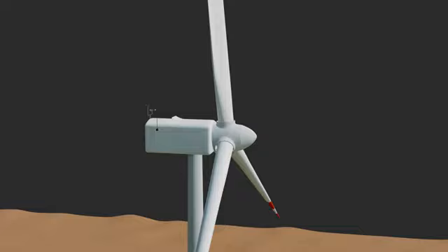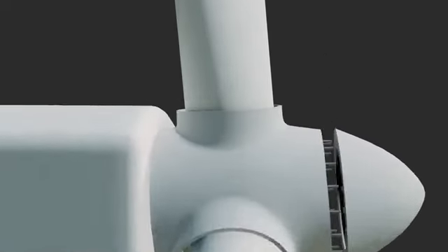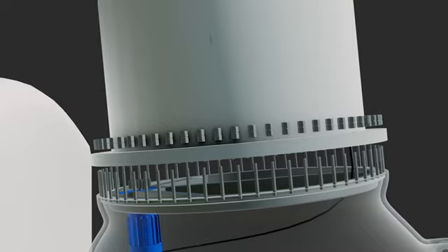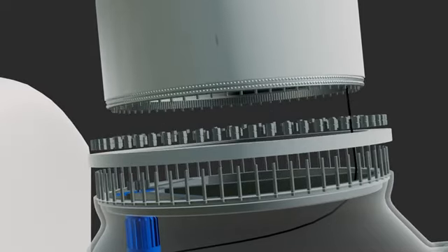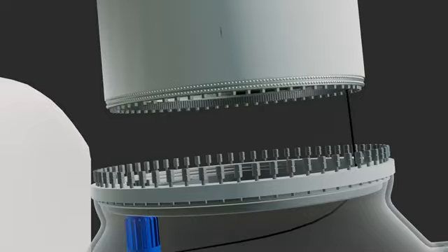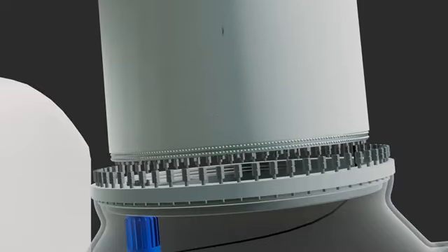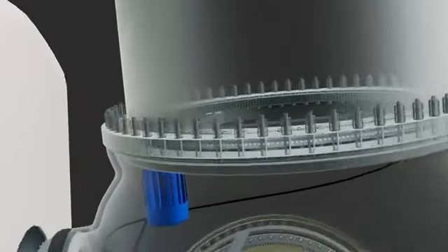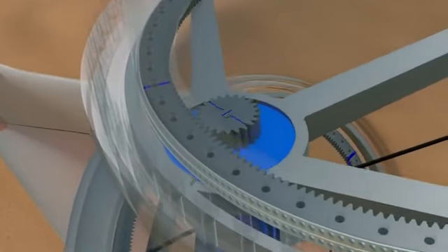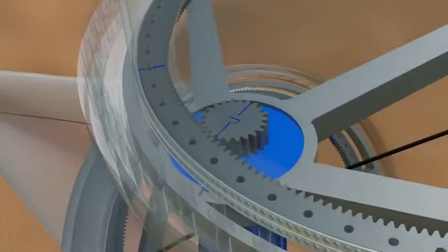An integrated bearing mechanism with an internal gear ring is present at the blade root. The outer ring of the bearing is bolted to the hub, while the inner ring is bolted to the blade. This bearing allows the blade to rotate around its own axis while maintaining a secure mechanical connection to the hub. A synchronous pitch motor mounted in the hub with a rated speed of approximately 1500 RPM is used in the pitching mechanism.